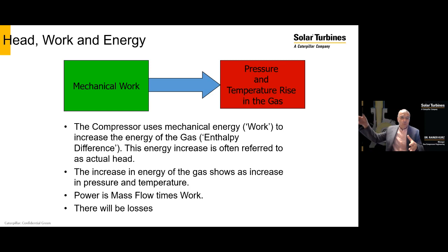Now, when I talk about work, I can also state that if I take the mass flow of gas through the machine, multiply it by the work that I put into that gas, then I get the power that I need at the compressor shaft. And in this compression process there will be losses.